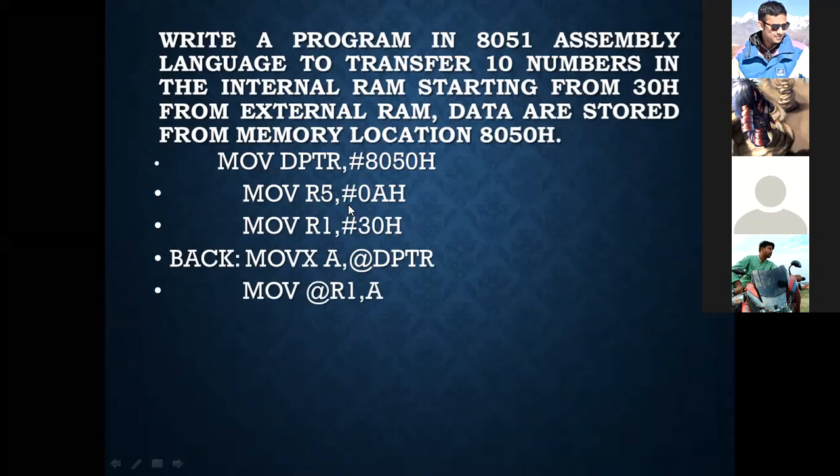So now what we need to do? We need to increment this DPTR. I mean increment this particular external memory location as well as increment the internal RAM location, and simultaneously decrement the counter, because one data has been already transferred. So how many datas are there to be transferred? 10 datas. 9 data. So this needs to be decremented. Okay, so 3 operations will be going on simultaneously.